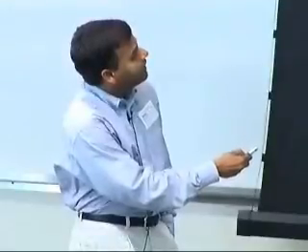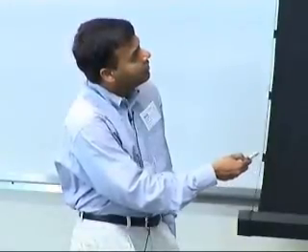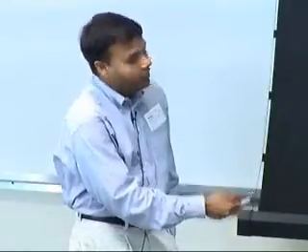So one thing that you could do, of course, is to say that, well, I'll connect the output of this combinational logic to this latch, and I'll connect the output of the combinational logic to this latch. Of course I could do that. And then you could say, well, now that I have these two latches, I could stick in a comparator, for example, and if there was an error, there will be an error flag which says that you got an error. Now that's not a very good idea.